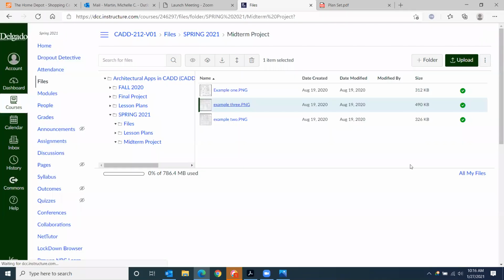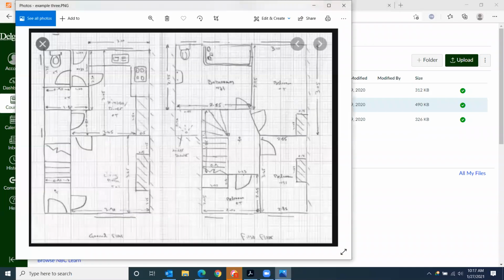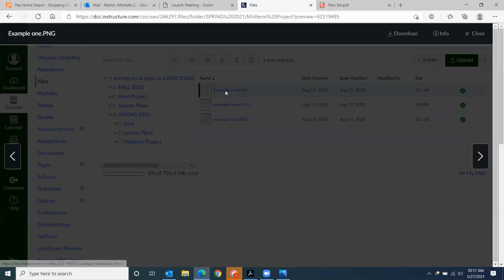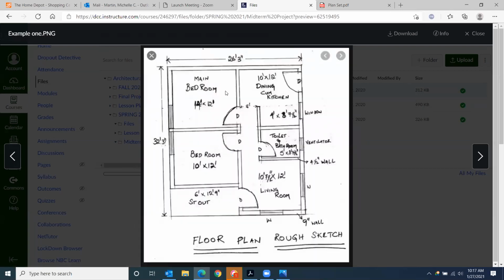Let me close this and jump back to this one. I know it's not great for all of it. So when we're actually going to lay out our dimensions in Revit, there are two ways we can do it. We can do it from wall to the middle of the window, like you had mentioned, or we can do it from wall to the edge of the window.